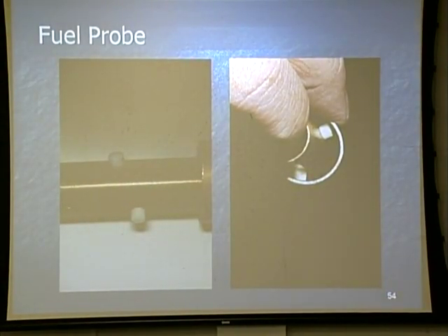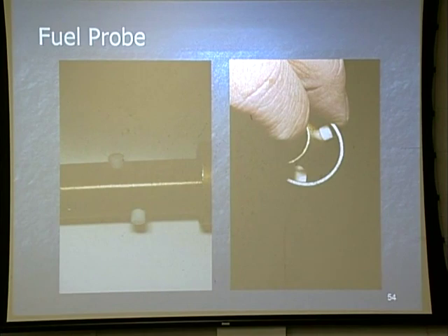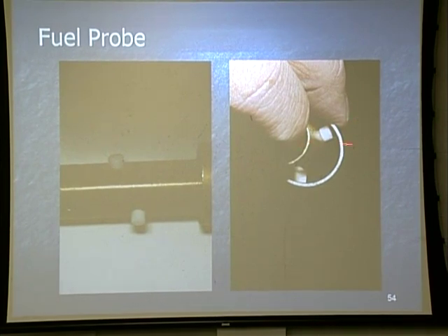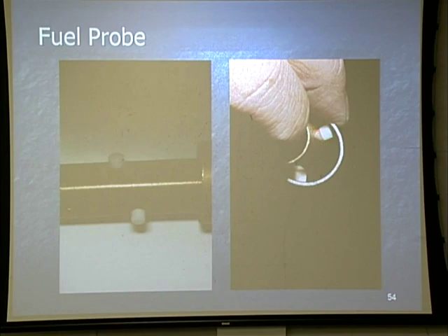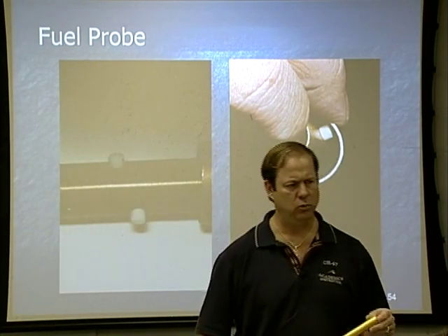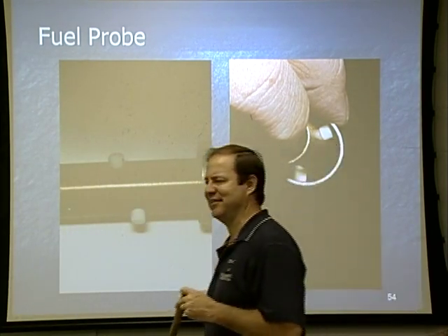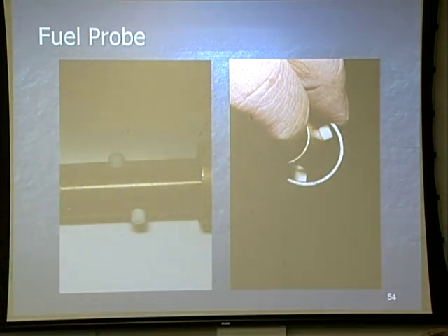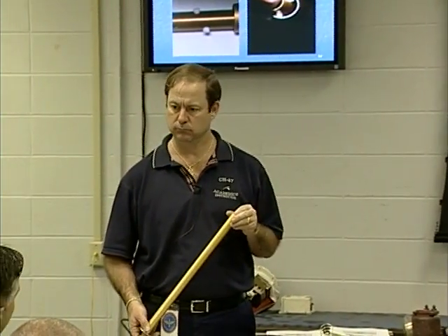And here's how it works. You have that inner tube and you have an outer tube, and then you have these little standoffs that prevent those 2 tubes from contacting each other. All right, now, this is a capacitance type system. Why is it important that you understand that it's a capacitance type system? Because it doesn't use a float. Okay, but what else? That requires electricity.